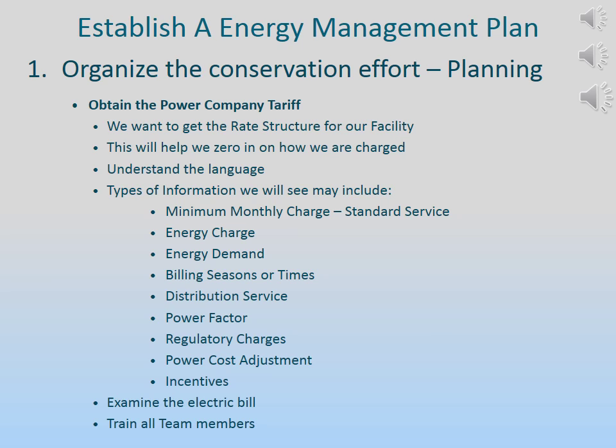But then the next time we start something that is over that value, it starts to ratchet again until we get to a locked point. After 15 minutes, it reaches some peaked value, and that is what we are billed for. We may have only done that one time a month, but we could be billed that way for a significant period of time. In this case, it was for 11 months. The point being, that is why SOPs are important. If we mess this up once, we are paying for it for 11 months. We have to try to stay with the procedure we established to control this.